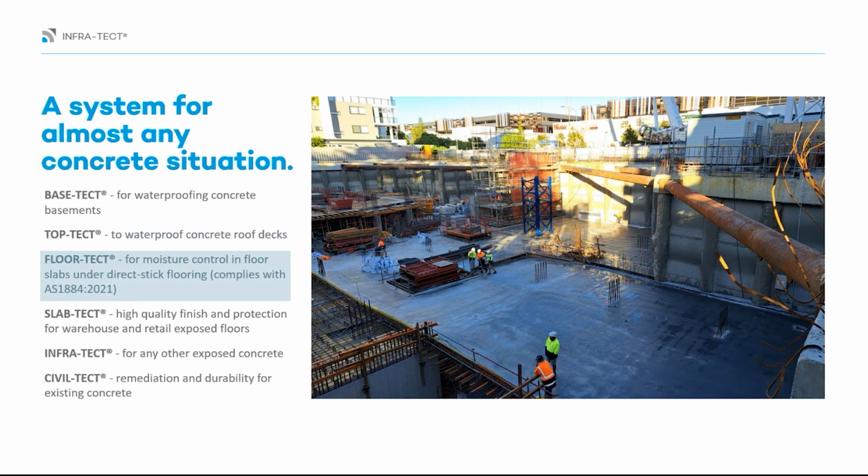FloorTech is one that we've had around for ages, but it's always been worded differently. FloorTech, again, is a more holistic approach to moisture controlling under flooring in hospitals, aged cares, those sorts of businesses where a lot of resilient flooring is used. Quite often there's lots of variations at the back end of projects with grinding and moisture control, where you can protect the floor from day one at a much lower cost. And it really speeds up that construction timeline as well.